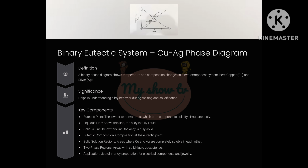Eutectic point, 779 degrees Celsius, 72% Ag, 28% Cu. This is the lowest temperature where the alloy solidifies simultaneously into two distinct solid phases, a Cu-rich phase and an Ag-rich phase.